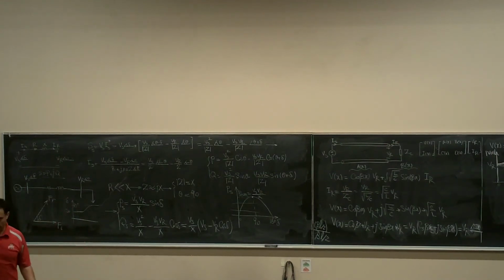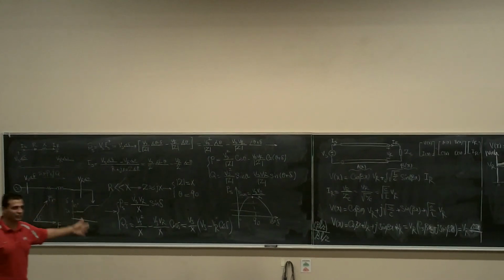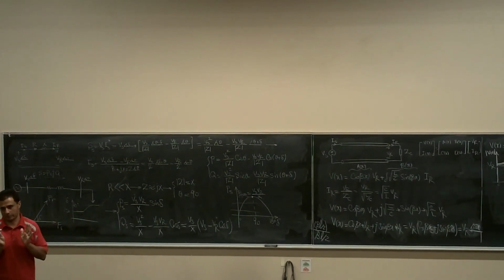That's one way. But another thing, you want the generator to be as small as possible, right? You're going to put it like 30 meters up there. So if it's a heavy generator, the tower has to be very powerful. It still is powerful, but you have a generator that is half the weight of the other one, and that's going to help you a lot with the structure. For the wind generators, those wind towers, they design them with a leading power factor, because a leading power factor is going to reduce the size of the generator.